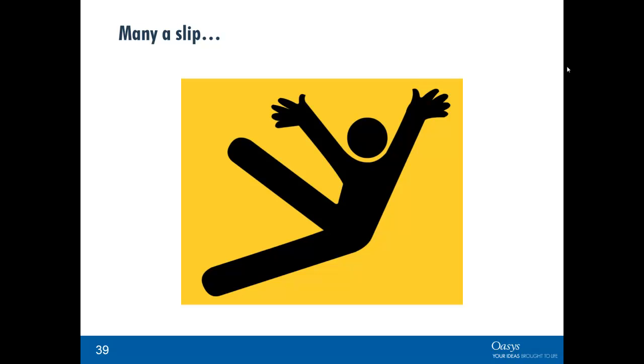So, summary, things to look at when things are not right. Check your units, check your materials, check your properties, check your loads, check your connections, and check your locations. And use the analysis options to help track down the problem areas.